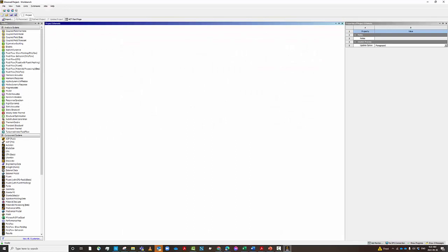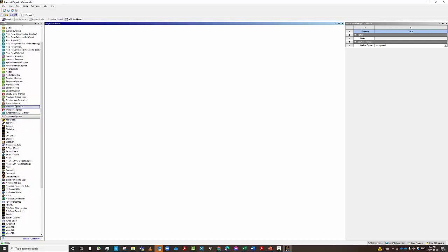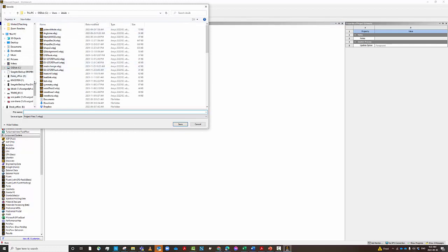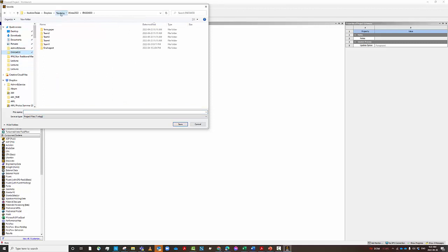So we are going to go here to select thermal. Okay, thermal steady state. Where is thermal steady state? Should have it here. Steady state thermal. Double click, and then, as we know now, you can type this. This is heat sink. Okay. And of course, as I told you, you always need to save. So I'm going to save this in my lecture folder, so when we start in the class, I can bring it back.